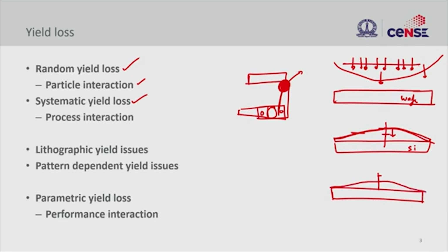So now my only yielding devices are within this range, right? Below this is all very thin, I'm going to lose those devices. Unlike the previous one where I have yielded somewhere here, but I have a window, right? So a window of devices where I was able to use it, but now you are reducing that window, right? So one needs to take a call on how to optimize the thickness for certain applications.